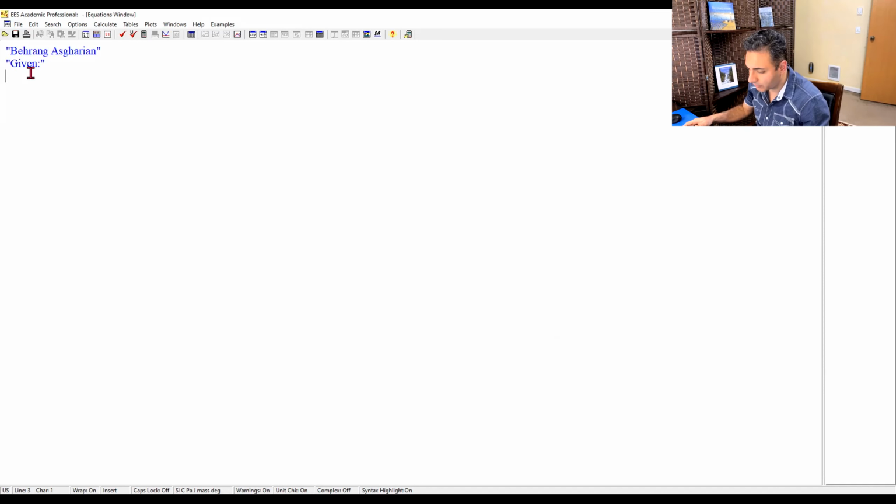So we're going to start with the given values. The given values are usually the values that the problem gives us, like the diameters, like the temperature of water, like epsilon. It says commercial steel, right? So let's get started with all of these very quickly. Epsilon equals 0.045 millimeters based on the Moody chart. Convert millimeters to meters like this.